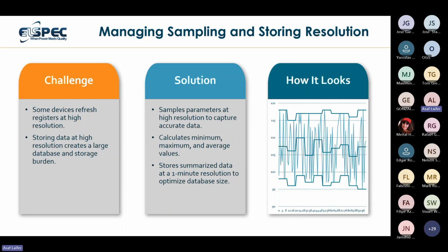But if I'm going to store this 1 second resolution, the database will be huge, especially if you're going to measure many instruments like this. Most of these instruments don't have the option to fetch a 10-minute average interval from Modbus. They will have the 1 second, maybe even faster resolution, but it's not an advantage, it's actually a disadvantage.